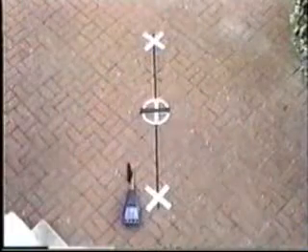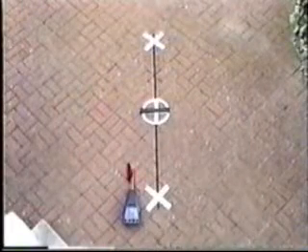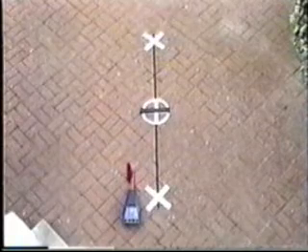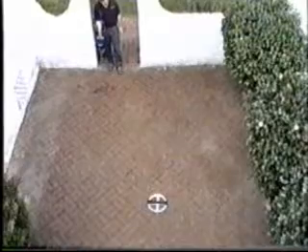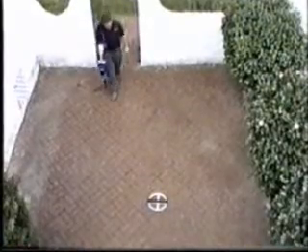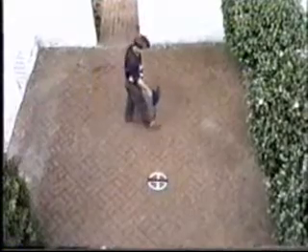To find the side nulls, place the receiver's antenna in the vertical position. Set the sensitivity of the receiver to low and turn the gain all the way up. Scan the area until a sudden dead spot in the signal occurs. If no dead spot occurs, then lower the gain and try again to find a dead spot. This break in signal is the first side null. Pinpoint and mark this null.